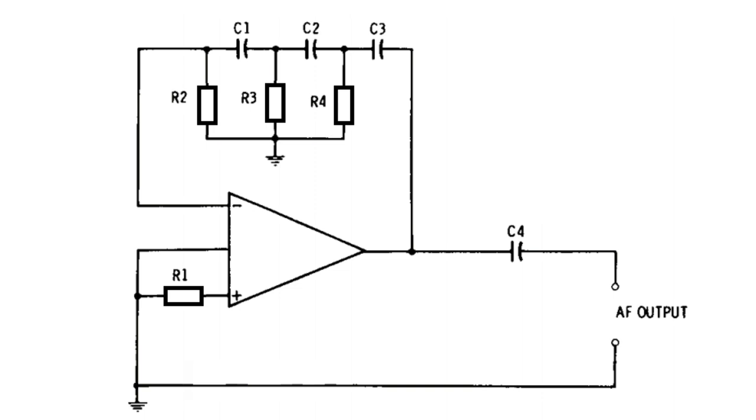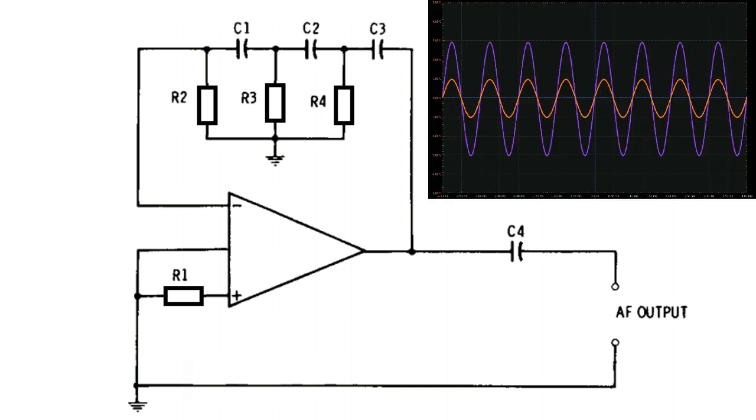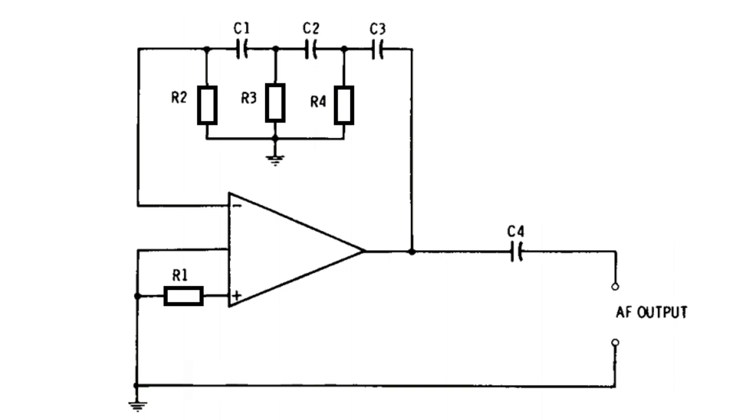But the circuit's attenuation increases as the resistance values are reduced, and this could lead to the output signal amplitude going down very fast with frequency, and oscillation may simply stop if R2, R3, and R4 are adjusted to lower values at high frequencies. Output control could be provided through a potentiometer, which could be either connected to the output of the Opamp oscillator circuit or introduced between the stages of the Opamp.